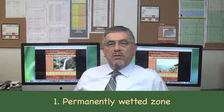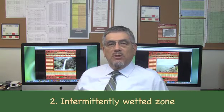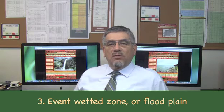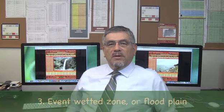Natural bank stabilization includes vegetated procedures to strengthen channel banks against erosion. For proper habitat functioning and natural bank stabilization, 3 temporal wetting zones are considered: 1. Permanently wetted zone. 2. Intermittently wetted zone. And 3. Event wetted zone or floodplain.